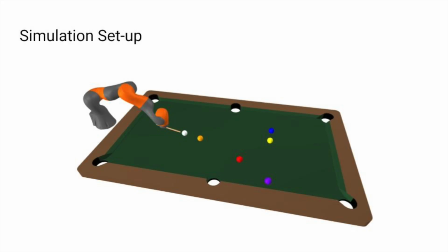Our simulation setup involved creating SDF files for the cue, balls, and table. Our pool cue is welded to the last link of the IIWA arm and uses a compliant hydroelastic collision model to replicate the effect of a leather cue tip. Pool balls and table use rigid hydroelastic collision models. We created the pool table with CAD, accurate to bar size regulation tables.